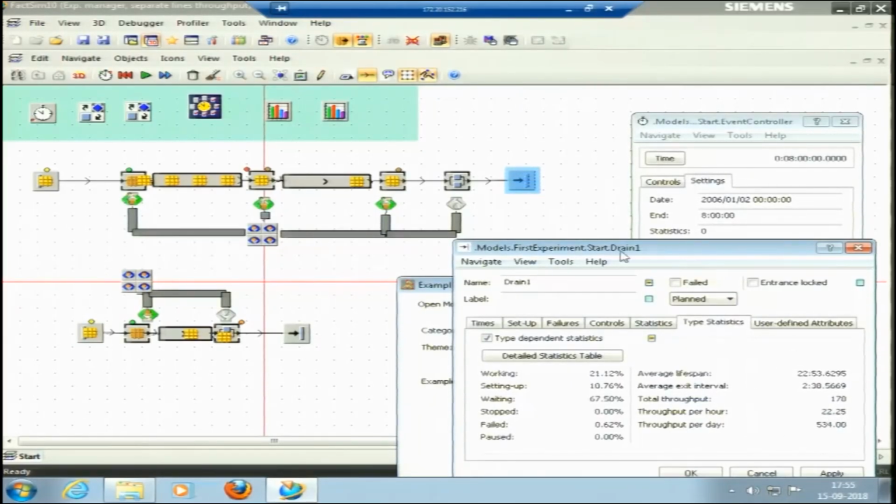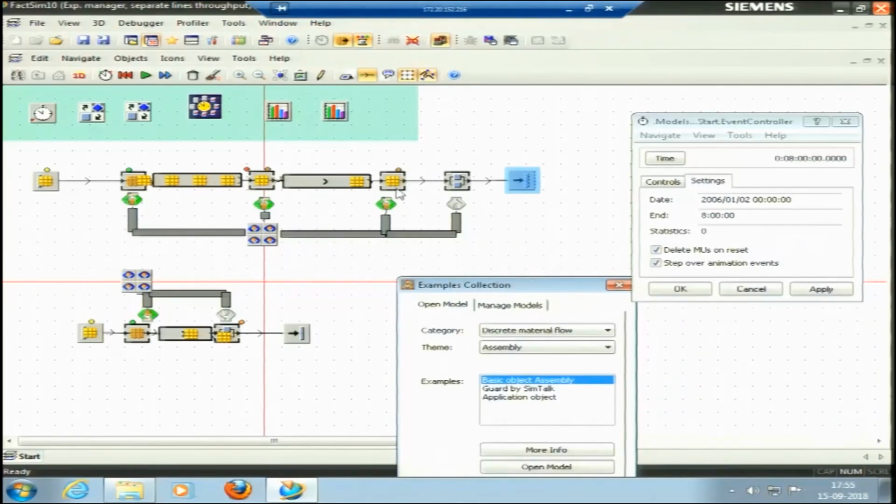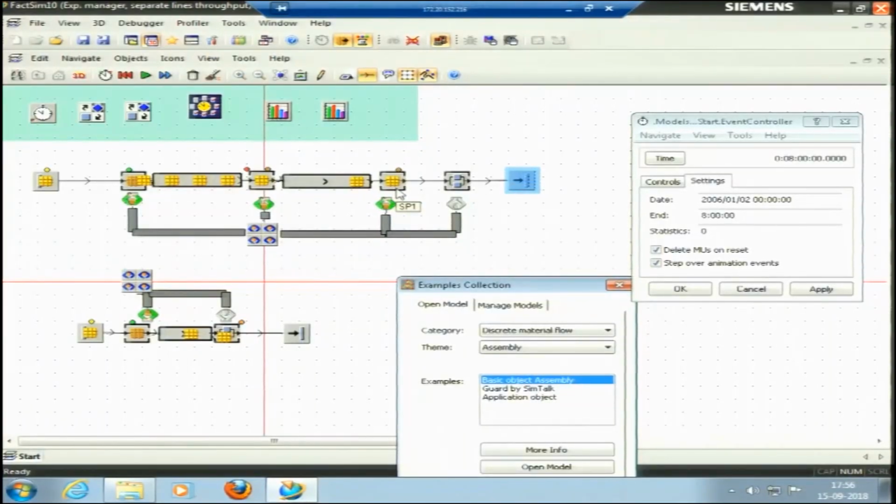This is based upon the input that we have given to the specific processes, which I will discuss. It is the setup time, processing time, then the availability: is it available for the complete time, or is it available for 95% or 90% of the time. Then we have the distribution. For instance, if it is a manual process and we do not have much data, only 2-3 data points previously available, we can pick maybe a triangular distribution. If it is an automated process, I can pick a normal distribution with very little variation, because the process is automated. Based upon the inputs that we give, the software will simulate and give us a throughput.